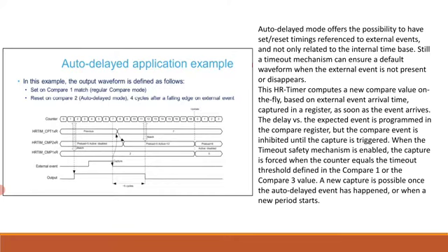When the timeout safety mechanism is enabled, the capture is forced when the counter equals the timeout threshold defined in the compare 1 or the compare 3 value. A new capture is possible once the auto delayed event has happened or when a new period starts.